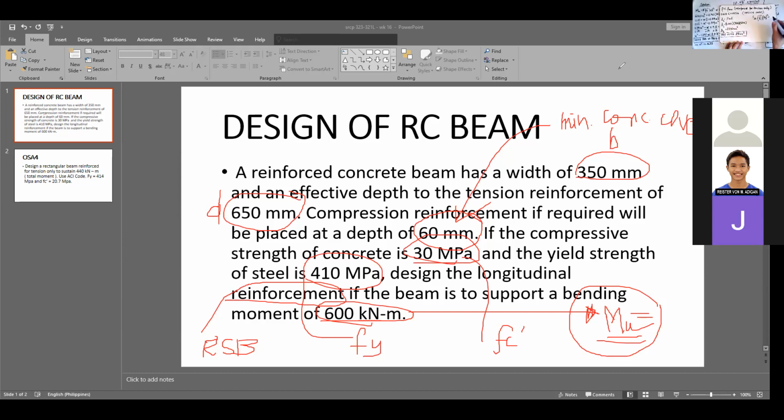And that should be equal to the area of the steel. So you can determine the number of 28 bars that you have to provide in the section by 2,730 total area of the steel requirement, times 4 over pi over 28 squared. So 4.4. So that means we need 5 pieces.